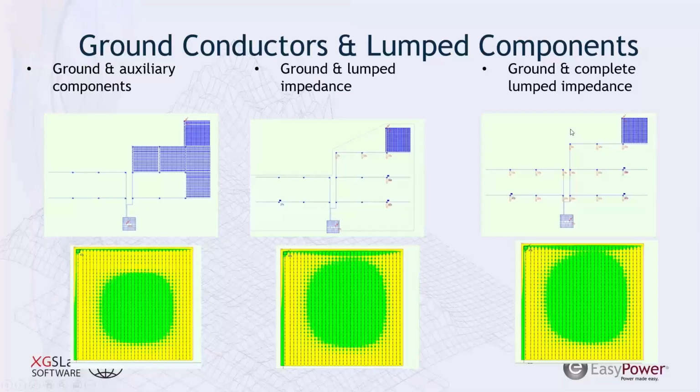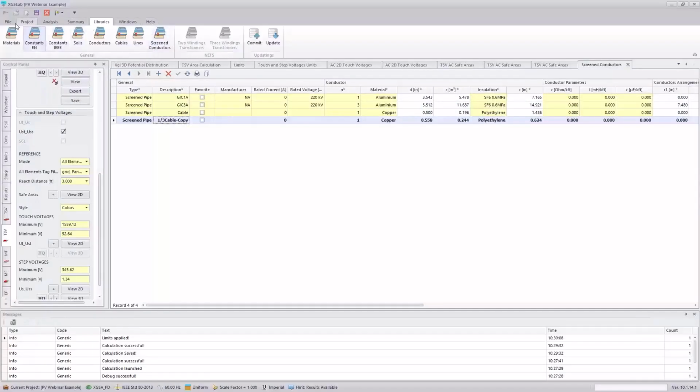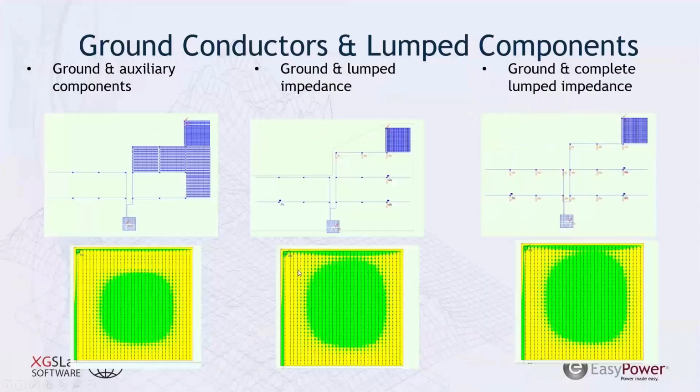So understanding where this region or this cutoff is going to be depends on your specific system's geometry and soil resistivity, as well as your electrical properties, how you're energizing this system. But that's something that you can look at through sensitivity testing, either with the scheduler tool. Over in the files, there's a scheduler that you can use to run different models, or just explore how this system operates in this different environment. So it's really going to be site specific.